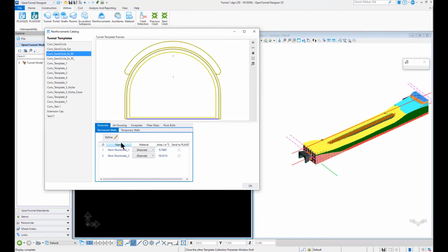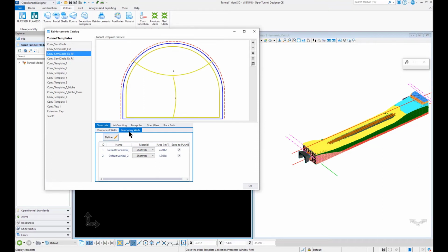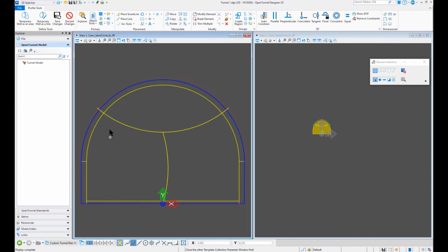And then the other one is this one, the temporary walls. Because we have three different soil excavation plans, we defined them. We need to stabilize the soil so that it doesn't collapse during the excavation. So we have defined two temporary walls, one is this one and one is this one. Once these are excavated, then we would demolish this temporary wall. Those are tagged through this icon.